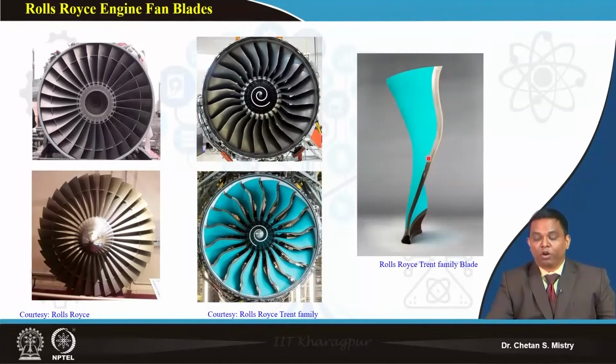Now if you look at the top side, this blade is having a thinner configuration. This particular section we are defining as the leading edge. The leading edge of my turbofan blade is having an elliptical or circular shape up to the initial stage, and then I will be having a sharp leading edge.